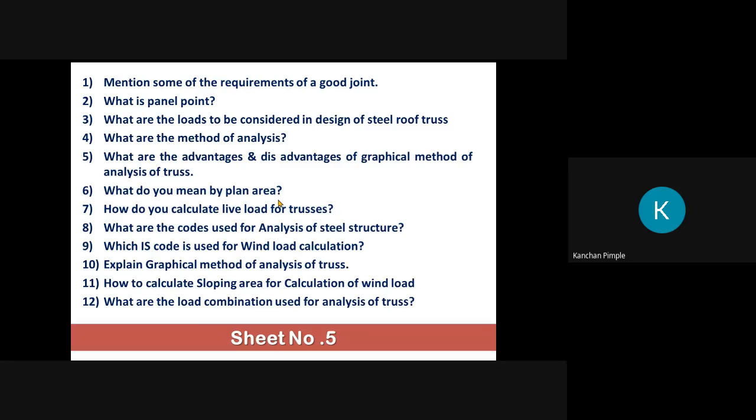The plan area is nothing but the span of the truss multiplied by the spacing of the truss. This is the plan area. Then, how to calculate live load? Do you remember? These are in IS 875 Part 2. There is one equation there, 750. Do you remember that?